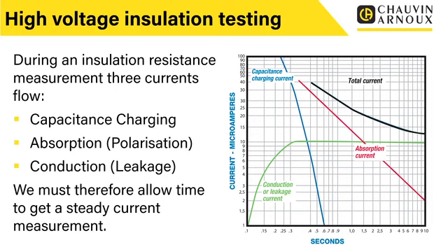Now, obviously, if we took the test readings or monitored the test readings during that time, we would get a changing value of insulation resistance, and it wouldn't be the true value of insulation resistance. So we need to make sure that we've applied the test current for long enough that we've got past that point at which the capacitance within the circuit is charging up.